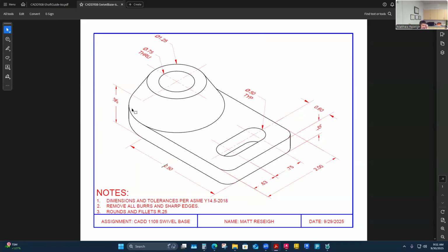So technically the round has a diameter with the base plate. Then I've got the cone shaped part. So I've got two features, I mean, it's one object, but it definitely has two features: a base plate with a slot in it, and then this cone shaped cylinder rather than a truly round shape. And so it's 2 inches in diameter. That'd be 1 inch from center out to the outer radius. So I feel like 3.5 would be the width of my front view. 3.5. I definitely think this is the top view surface here.